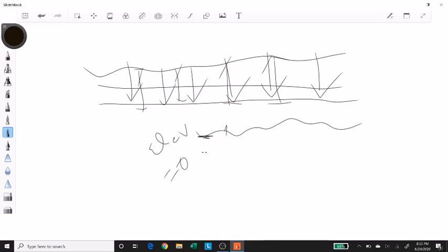Then when I find out the heights of different points, they will be from this reference line, which has a height of 0. And whatever the height difference between these, these points will have values greater than 0 if they are above the point, and if they are below the line, they would have elevations in negative.